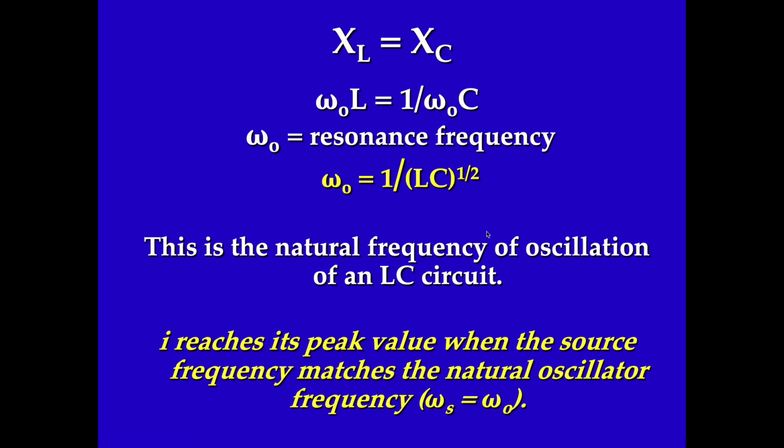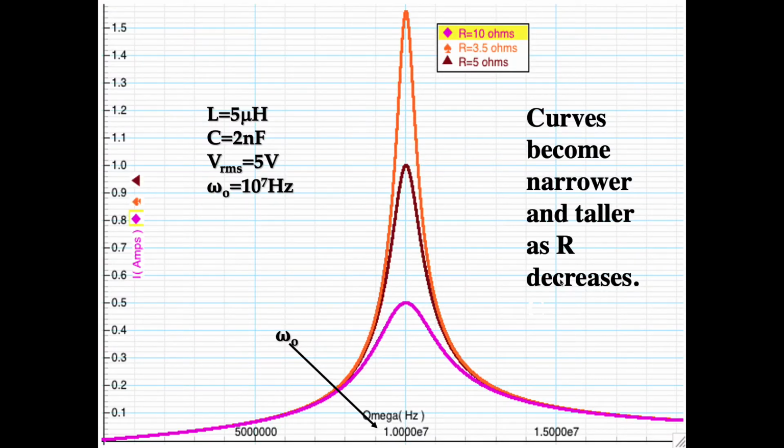Is it the frequency of an LC and not an RLC? Oh, you want me to repeat the question? Well, it's the same, right? I mean, for either circuit, it's the natural frequency of oscillation, though, right? Yeah, I was just asking if it is the same for the RLC. Yeah, it is, it's exactly the same, because the R is not going to affect it. And in fact, I'm going to do a parallel one, and the natural frequency of oscillation will have the same expression.